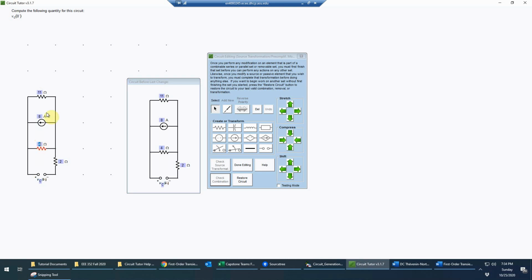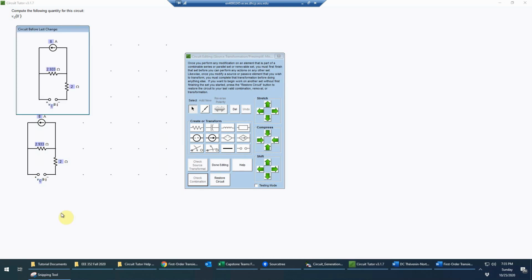So basically that would be the product over the sum for those two resistors. So that would be 44 divided by 15. So just doing that on my calculator real quick, that will turn out to be 2.933 ohms. And then this one has to change to an open circuit. So I just push the delete key, or I could come over and do it there if I want. That's gone, and now I just check that combination to see if that was correct, and indeed it was. Okay, so now is there anything further I can do?